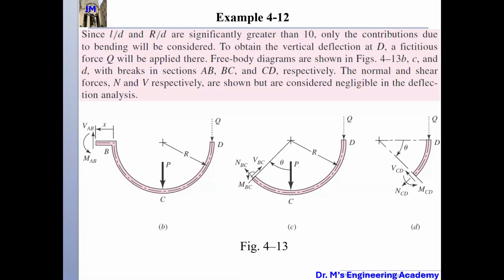Then we go through each of these segments, using the moment balance equation, because we only have moment here. Using the moment balance equation, we express the bending moment at any generic point x. And then we just plug in here. We also get the derivative of M, which is here. Then plug in, and then we do the integration. We go through all these segments. Questions?